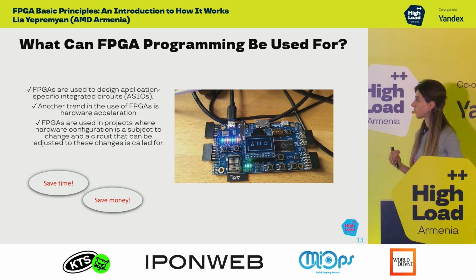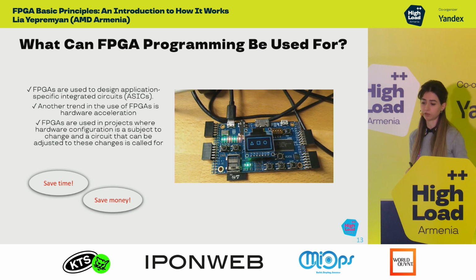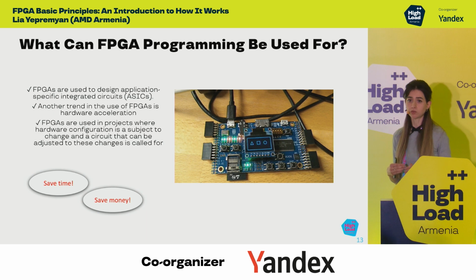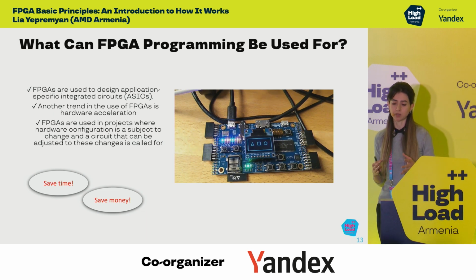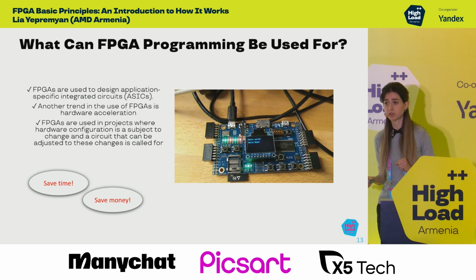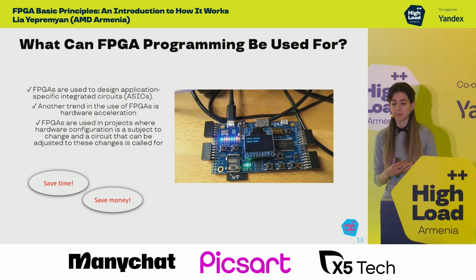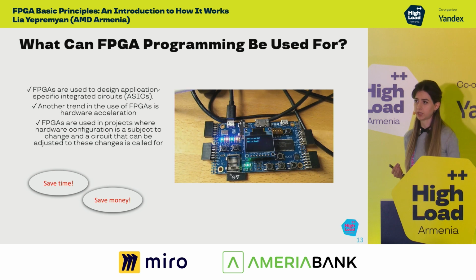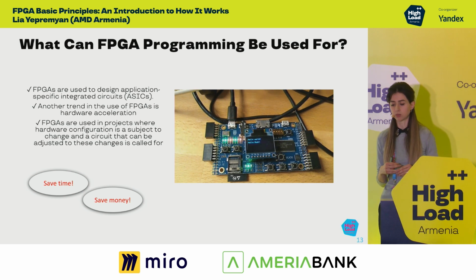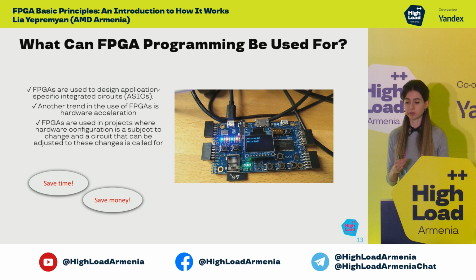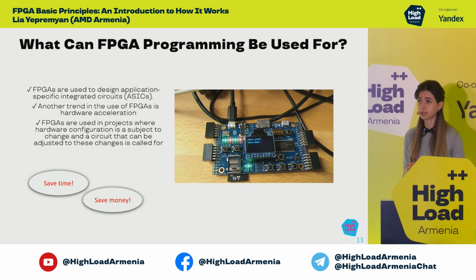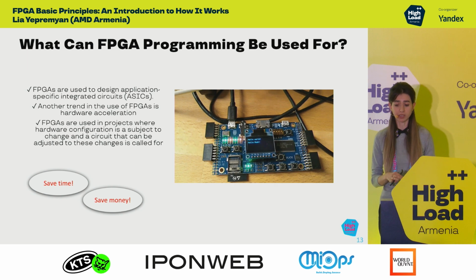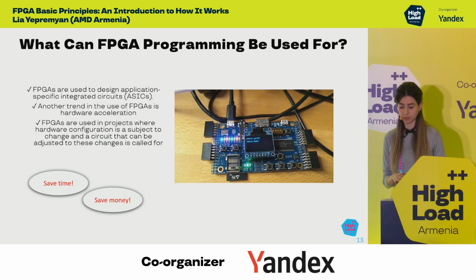Using software, we can configure FPGAs. This software is generally provided by the FPGA suppliers. And using this, we are compiling our FPGA. First, we are compiling by synthesizing and placing and routing all cells and logic blocks to implement for the target FPGA.